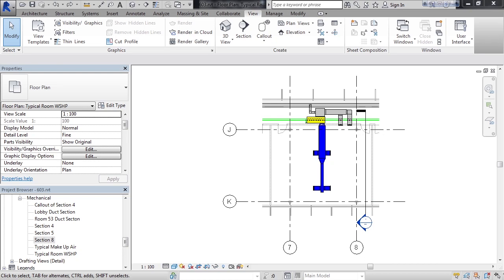In this lesson, we'll cover sections. A section is a cut through a plan or your three-dimensional model to show you an interior cut or face or a real-life 3D view of that area. For example, I would like to see in detail the HVAC unit and ductwork inside of this space. I can't see it through current elevations, so I'll make a section at a specific point or line and view from that area.